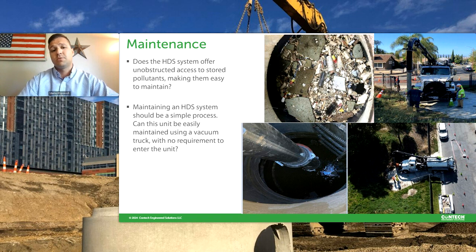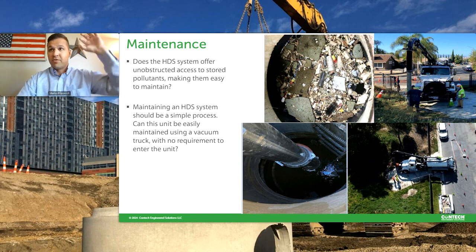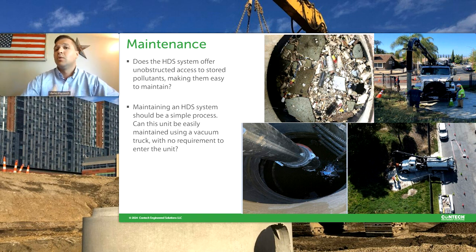You don't want to see the disruption of a landscaped area. You don't want to have overhangs and utility poles right above the boom of that Vector truck. So again, just something to consider early on in design here. Maintenance is becoming more and more prevalent and enforced. More cities, more states where we're seeing the need for that. And with these maintenance cycles, it's going to vary. Taylor mentioned Keeneland there in Lexington. If you have a huge stadium with hundreds of thousands of people and there's debris and cans and plastic cups and everything running in there, it probably makes sense to inspect that.